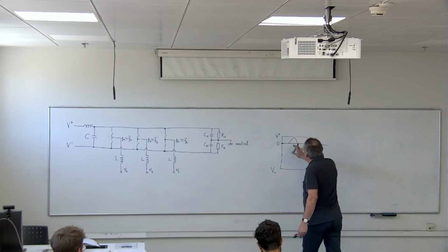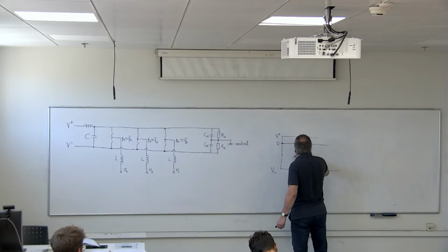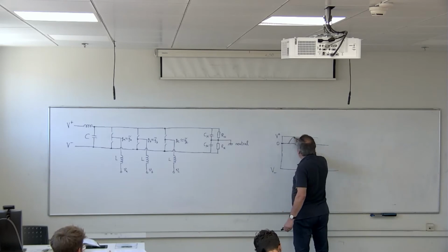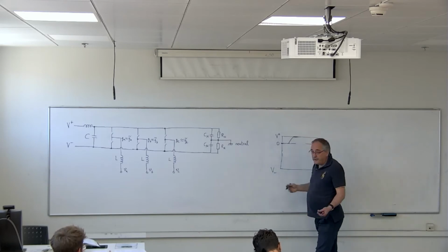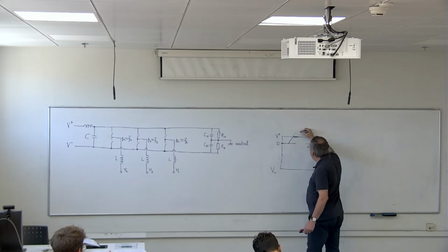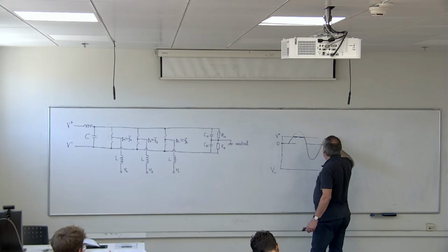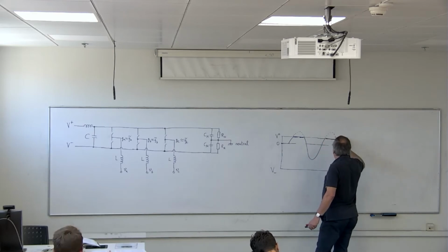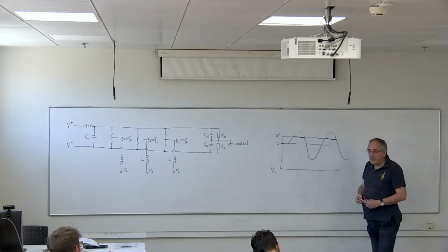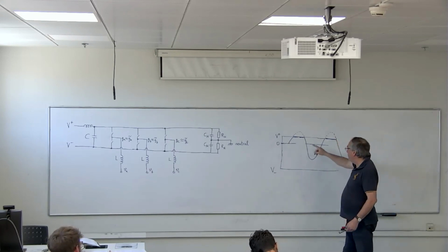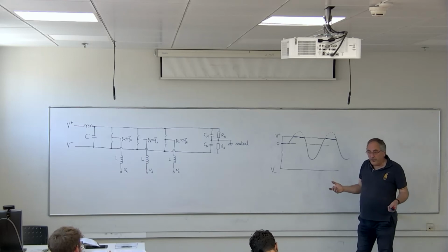Or if you try, then you are in trouble, because then you hit the upper boundary and you cannot go higher. So your sine wave will be clipped. It will be clipped, and then you can go down, and again here it will be clipped, and so on, which is a situation you don't want, because such a waveform has a lot of harmonics.